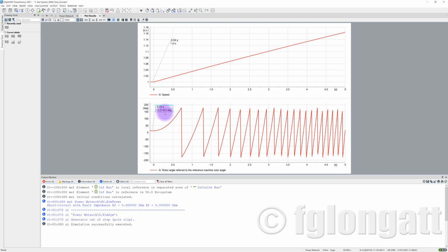However, all my students are extremely clever. They took a class about power systems in the previous semester, and they understand clearly the model of the synchronous machine. But coming back to my explanation, you can see over here, this is the initial rotor angle, and everything is fine. But the problem is that when we have the short circuit at t equals 0, the short circuit is inserted. And as you can see over here, the rotor speed starts to increase.